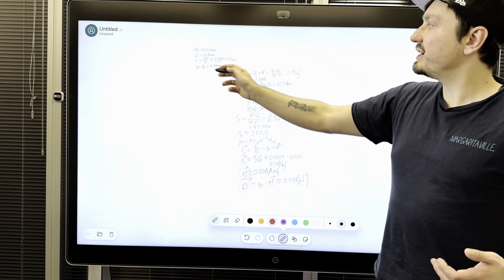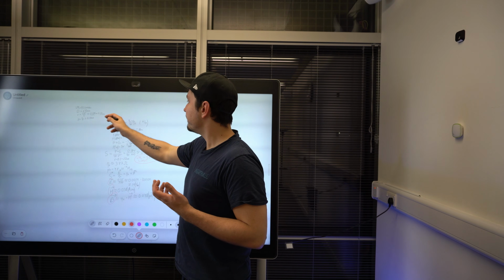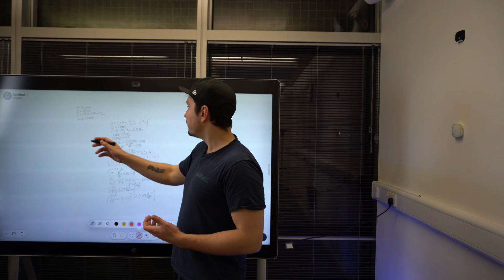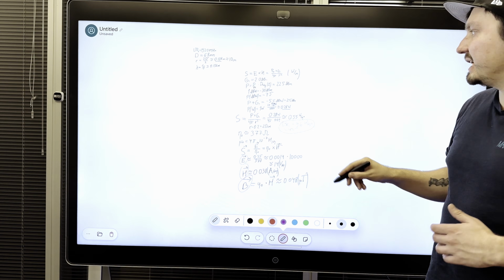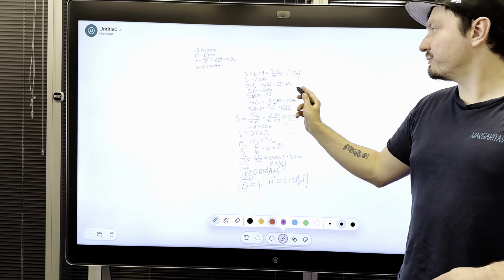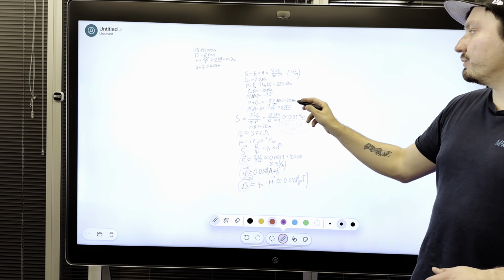So first of all, we established where the far field distance is and whether or not we can apply the far field formula. So we can, then we applied it, and then we converted from different units of measures from dBm to dB watts to obtain the power in watts.